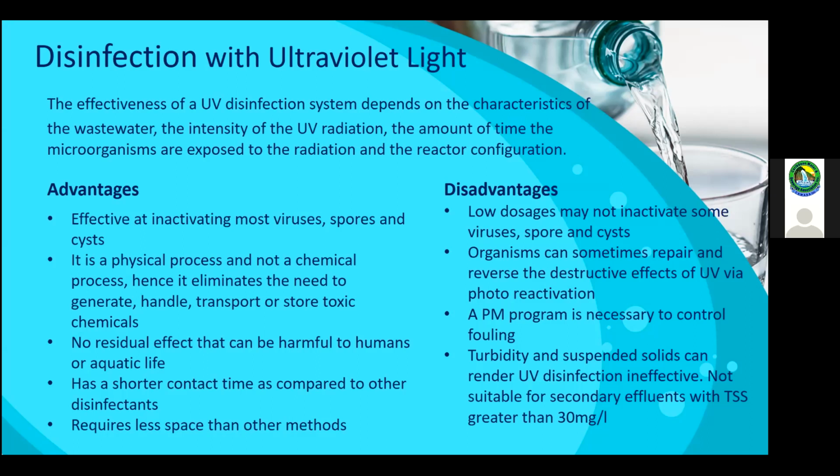When we look at disadvantages, low dosages may not inactivate some of your viruses, spores, and cysts. Organisms can sometimes repair and reverse the destructive effects of UV via photoreactivation.